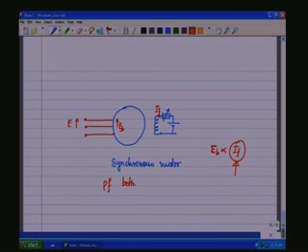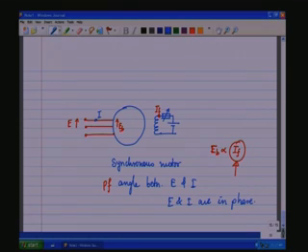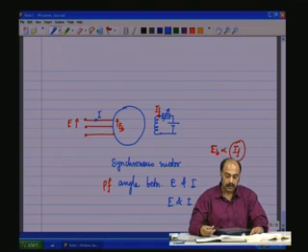So by controlling IF, by controlling this resistance, you can adjust the power factor angle between E and the input current I, and keep adjusting IF such that E and I are in phase, so that the mains sees a unity power factor, whatever may be the load across it. So this would be another interesting application of the synchronous motor.